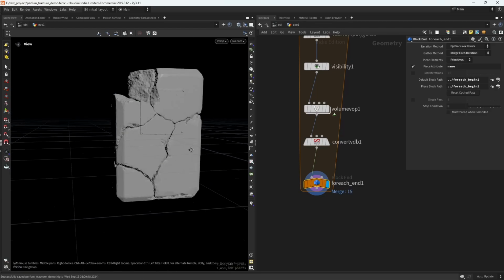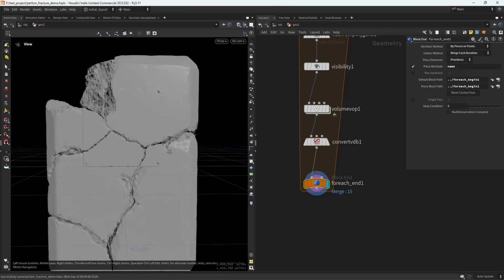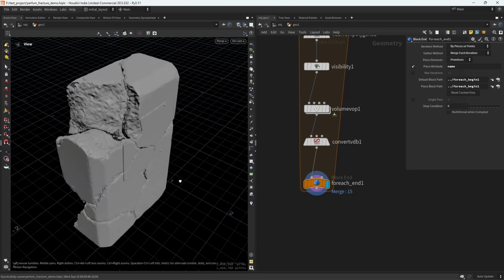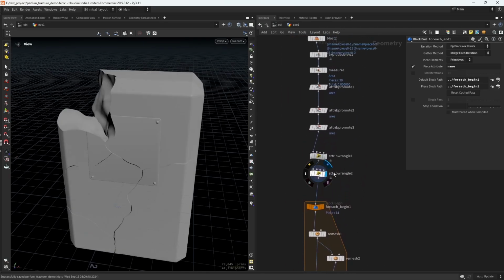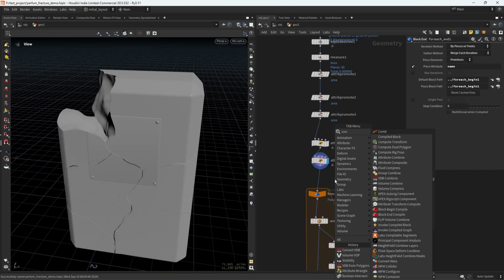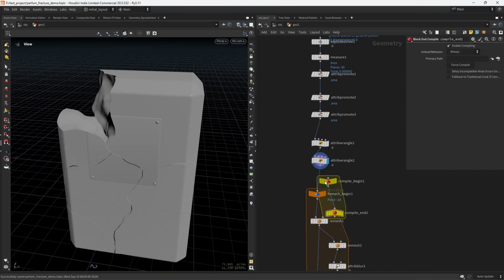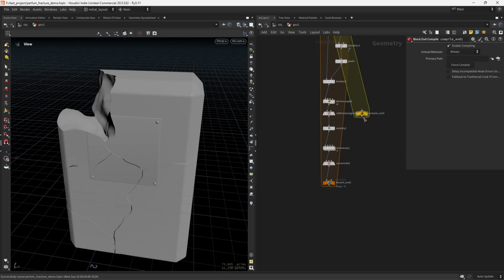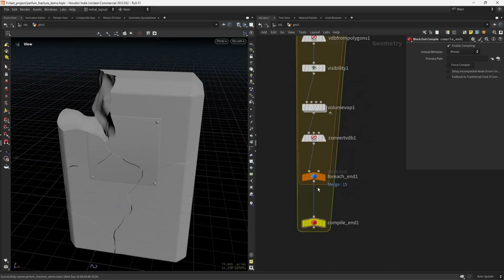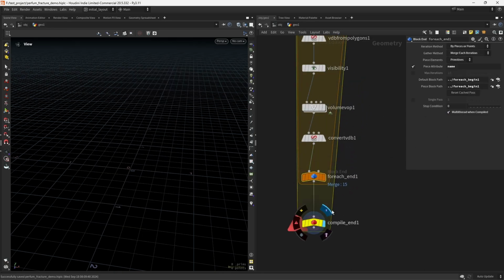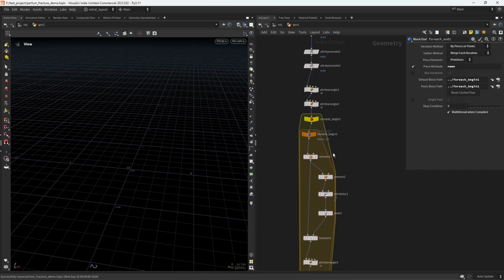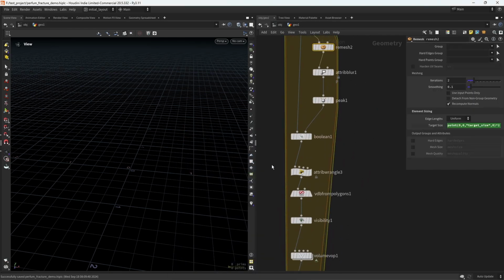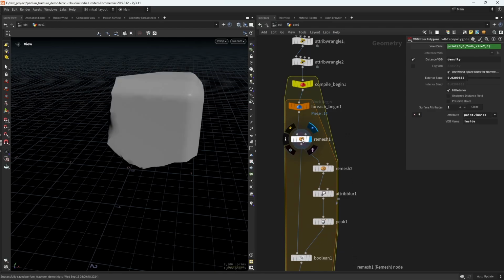And this will take a while, as you can see, but in the end we will have a nice result. The thing is, this will take a while, so we need to compile it to be more optimized. So let's select the first node and create a compile block and connect this in here and enable multi-threaded. And of course we will have an error because we are using direct reference in this remesh and VDB nodes, so we actually need to use spare inputs.